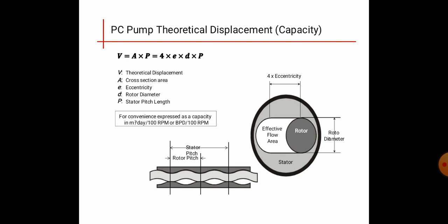In the lower diagram we can see that there are different number of cavities, various number of cavities. In these cavities the fluid is trapped between the rotor and stator body, and the pressure is generated.